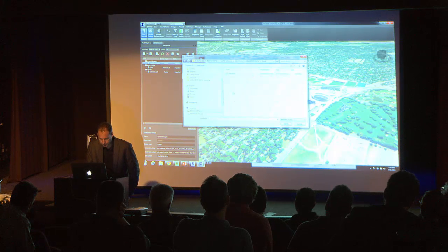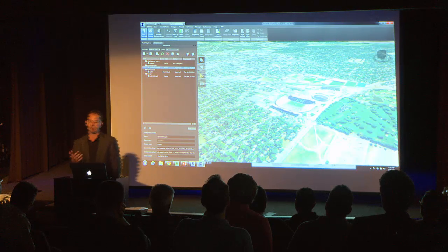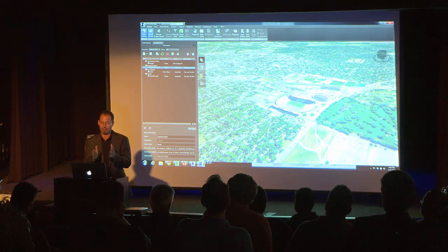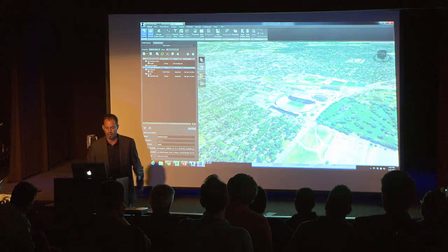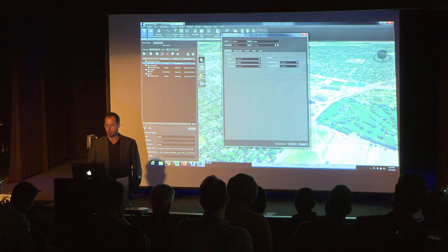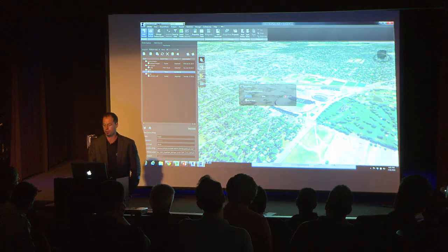So in this case, let's bring in some roads. Literally, it's just a shape file. If the shape file has assigned in here 2D or 3D, if it has 2D, 2 lanes or 4 lanes, it will draw it that way. As long as someone entered the information, it will put this in here. So again, you just tell it what you brought in. In this case, I'm bringing in the roads. It's going to automatically do the refresh.